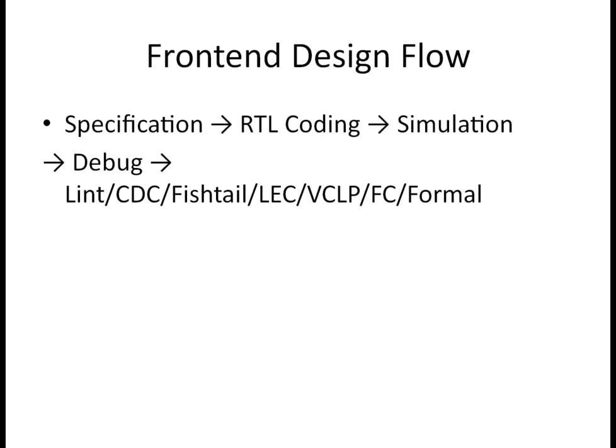As I mentioned, the first rule is inferred latches. Inferred latches mean if you are writing a case or if-else statement and the else is missed in your code, the tool will mention that a latch is inferred in the design. The tool will give an error that a latch is inferred, and we need to fix the violation. We need to open the RTL code, check through the schematic in which part of the code the latch is inferred, and accordingly fix the code.